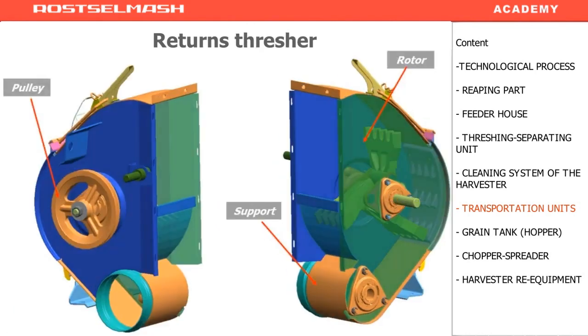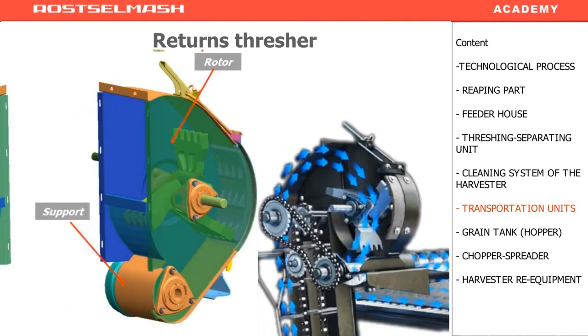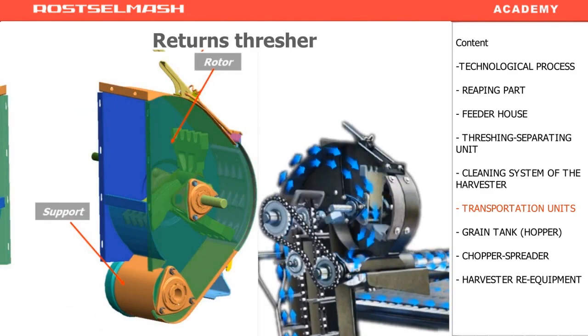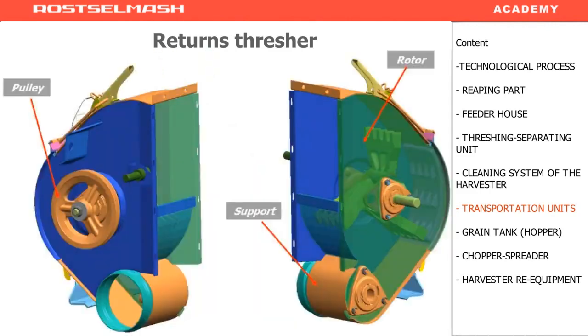The rethreshing unit has got 3 rotors, which thresh the unthreshed wheat heads against the concave. The concave can be easily dismounted to inspect for damages. You can also inspect the mechanism itself or the rethreshing part. To do this, take out the stopper, unlock the clipper, and dismount the concave.